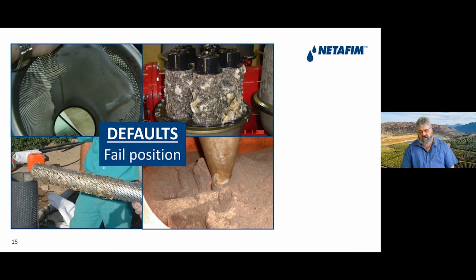Over time, the sharp corners of the sand will be ground down, and then your filtration will be different, and you need to replace it. In some cases once a season, sometimes every second season, just depending on your water quality and also how often the filter will actually backwash, how hard the filter will work.